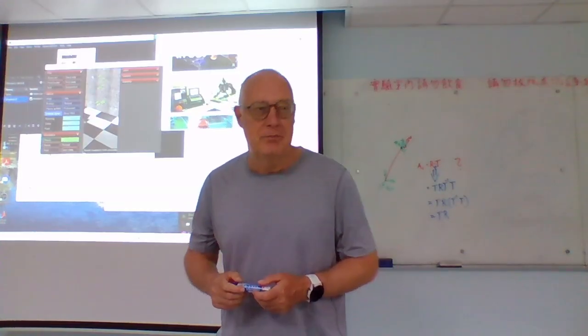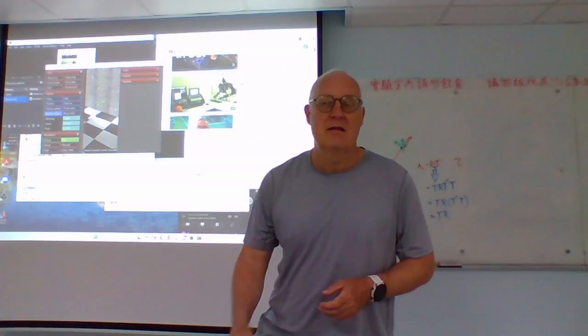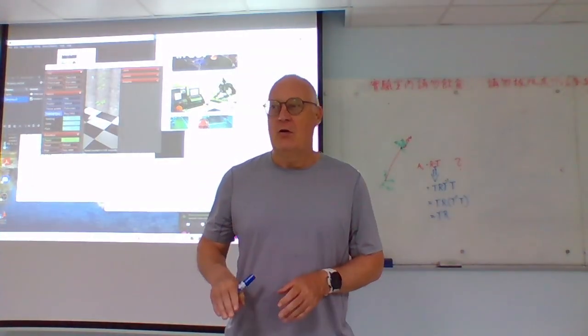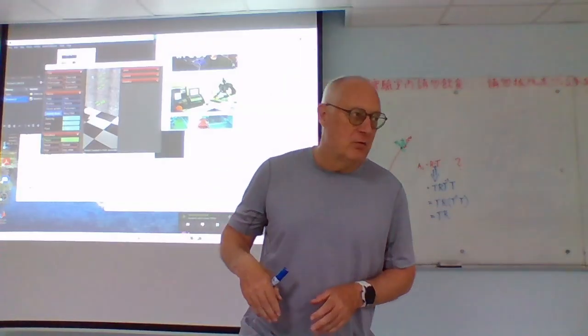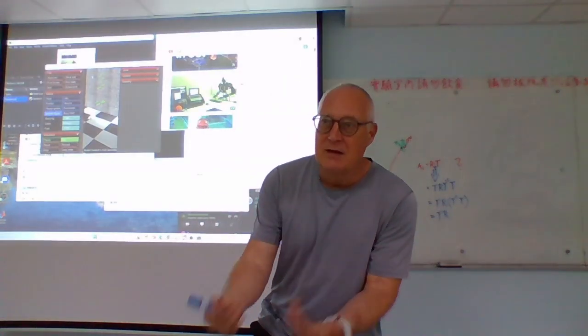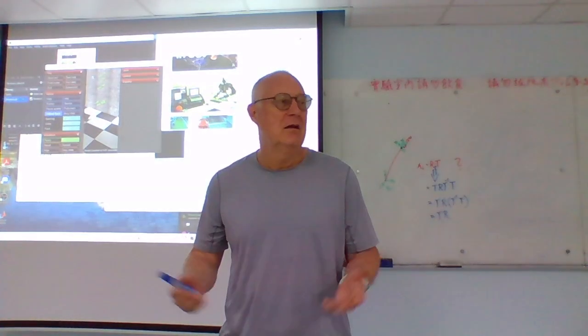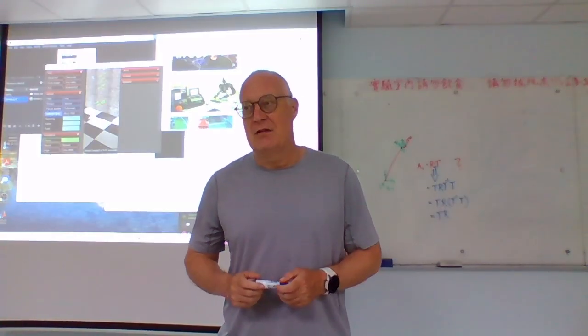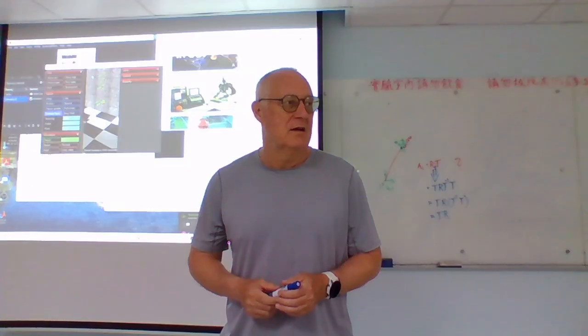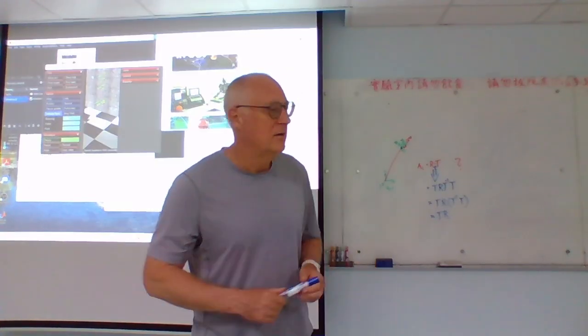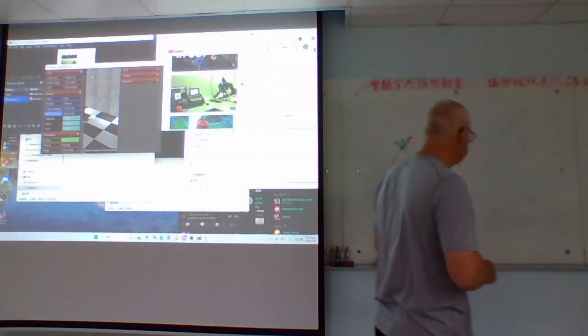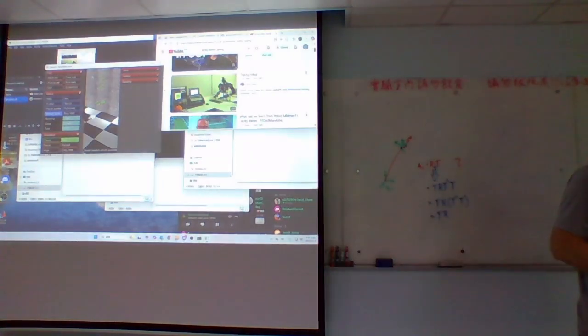So, for example, you specify that the knees on the humanoid robot always must bend forward, never the other way. Then that means that you get rid of that singularity at that point. Then you know which way to move. So this is a very short, brief introduction to forward kinematics.